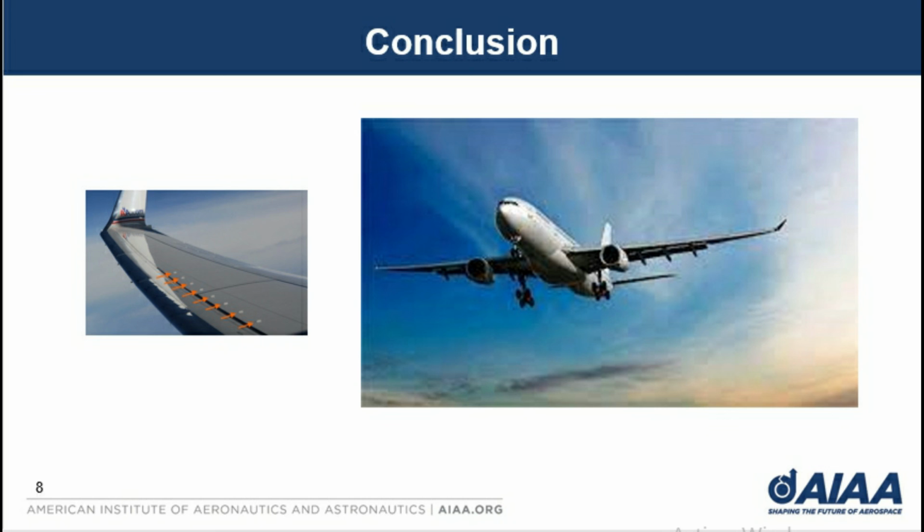In this study, we mentioned some of the methods that are still in process of research and other ones that are already in use in some aircraft. So taking this into account, we can say that the most practical of these methods will be the vortex generator. It might not be the most efficient one, or the one that makes a really great change in the boundary layer control, but it is the simplest one that shows an improvement in the delay of the detachment of the boundary layer. The second one might be the local heating of the wall.